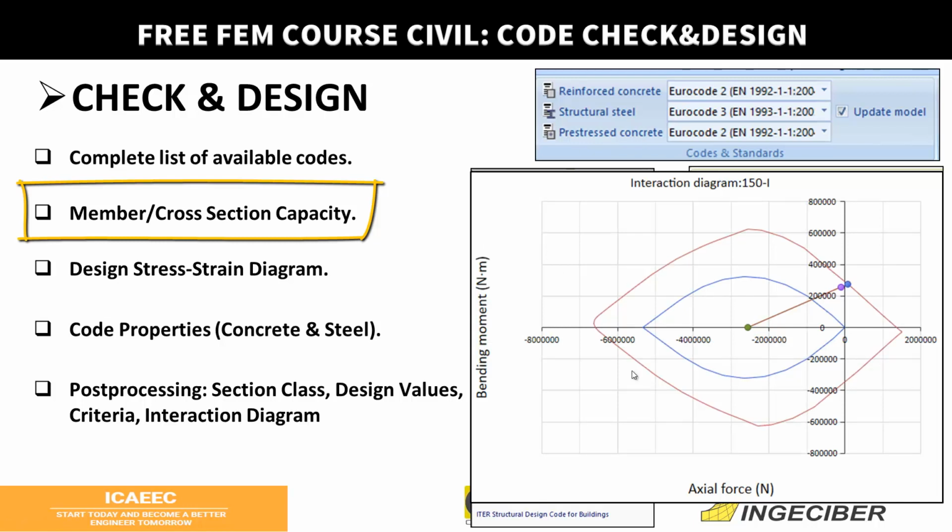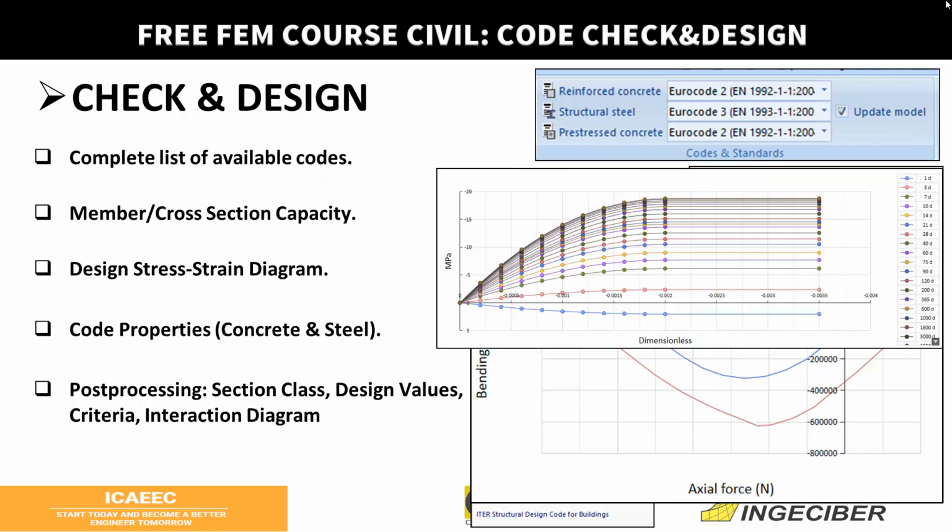and for steel structures, this ratio of demand and capacity, which is the total criterion, will be calculated depending on the checking type, whether it's tension, shear loads, bending, or combined forces and moments, according to each code's specifications. For the check and design process, you can select another design stress and strain diagram, different from the analysis stress and strain diagram, for steel, concrete, and prestressed concrete checking.